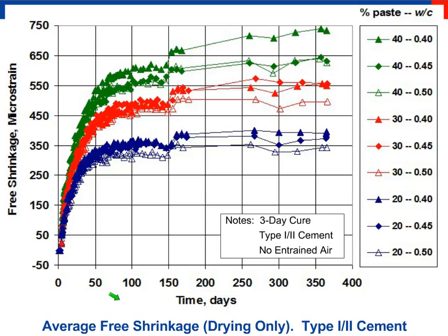And so one of the things we observe is, first, the water cement ratio. A lot of people think water cement ratio controls everything. Well, it doesn't. It has a big impact on strength, but it certainly doesn't control shrinkage. And we can see that water cement ratio is not the governing factor. It's just how much cement and water together we have.